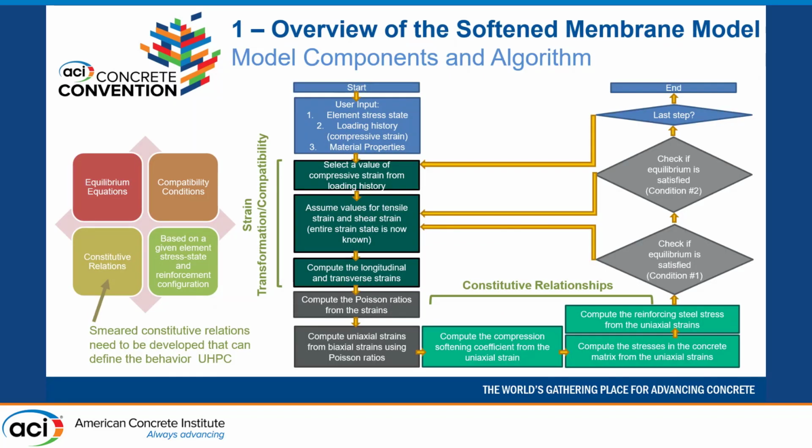Okay, so the components of the model. The basic components of the model are the equilibrium equations, compatibility conditions, constitutive relationships, and obviously that you know what stress state your element is subjected to, right? So whatever stress state you're trying to investigate, whether it be pure shear or shear combined with axial effects.